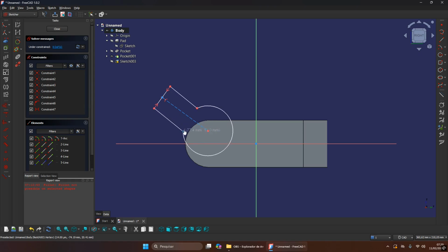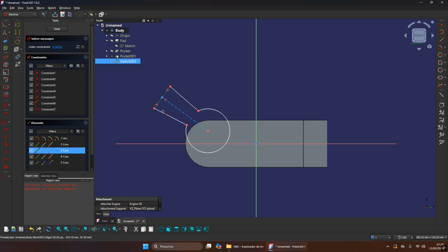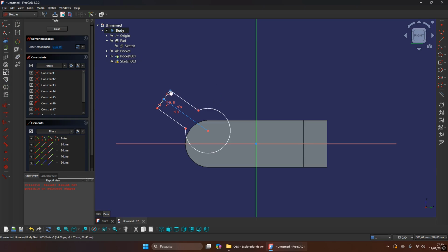those two on the other side won't. Instead of creating a symmetric relation here, I'm going to just create some perpendicular relations. Go to constraint perpendicular, select this line and this line, and same thing here, this line and this other line. Okay, if you do that, now it will be similar to these two points here. They will have a similar condition, which is a symmetric relation.